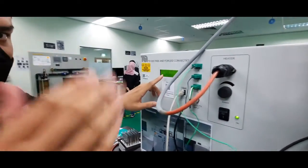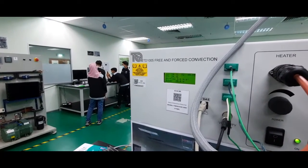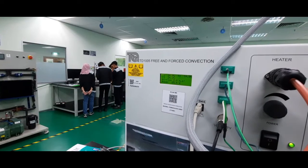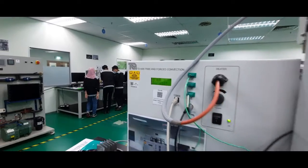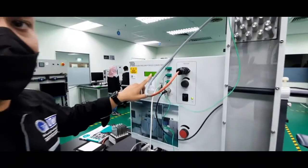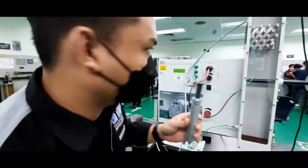After that, set the airflow to 3.0 meter per second. Now we are done setting the airflow to 3 meter per second. Now we use the probe to gain the temperature, and the probe represents T3 or temperature 3.